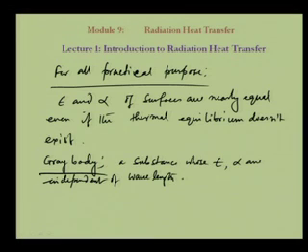As we have discussed, epsilon equal to alpha, that is Kirchhoff's law, emissivity equal to absorptivity, is valid for a particular wavelength and for black bodies.